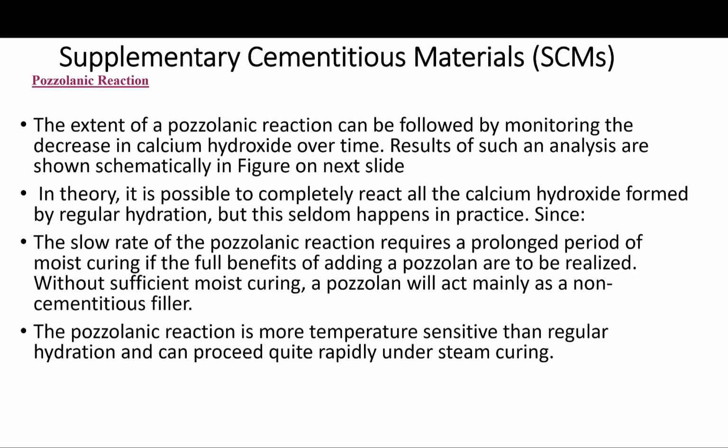So this is really something for the practicing concrete professionals, the site engineers and the construction professionals to remember, the benefit of moist curing, because almost every concrete mix you will deal with on your site will have some type of a pozzolan.